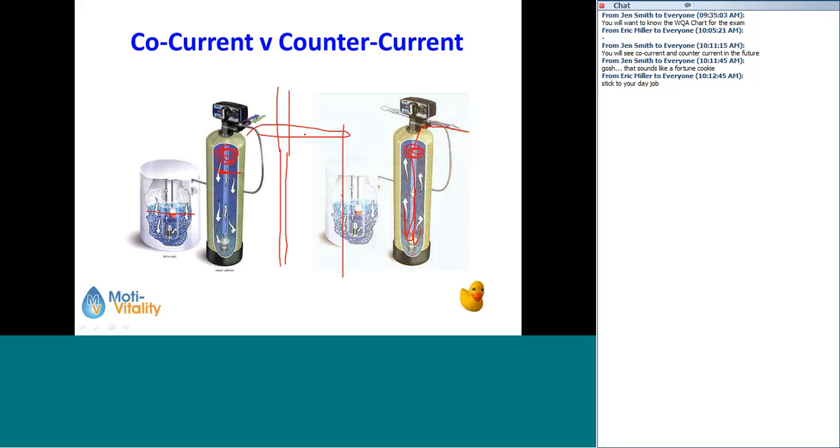If you're cleaning co-currently, then the water can come down here, and you might form these little anthill looking things, like streams. So the water may form a path that comes through these little channels here. It's not always going to do this, but it can, which means that you clean the resin through here, but not necessarily as well through here or through here.